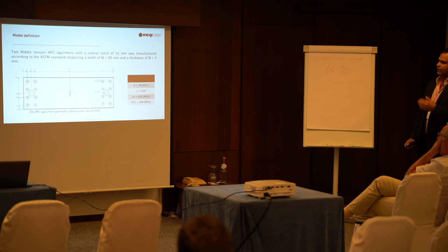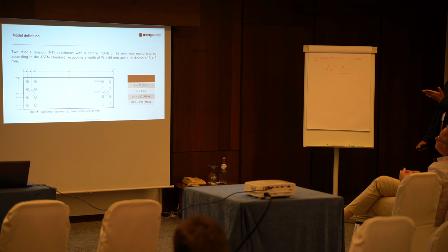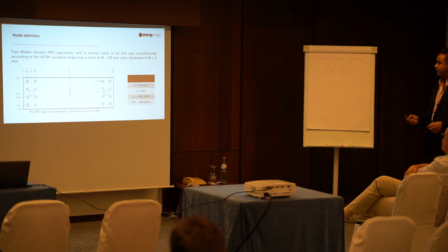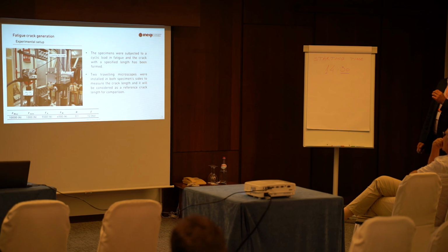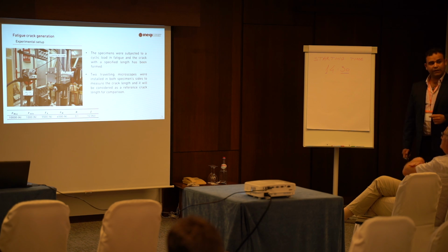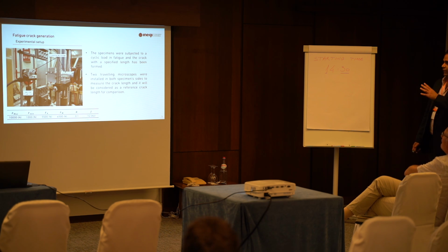This is the geometry of the MT specimen, with the material properties from the literature. It was manufactured based on the ASTM standard with a width W of 80 millimeters and a thickness of 3. The notch was 16 millimeters, manufactured by EDM. First, the specimen was fatigued at a ratio of 0.1 with a maximum load of 10 kilonewtons. It was a normal fatigue analysis.